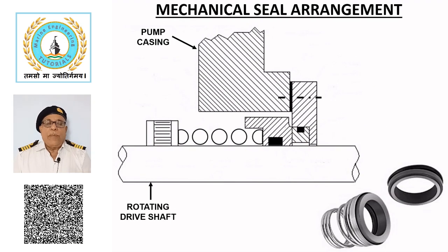Mechanical seal arrangement. This sketch shows the mechanical seal arrangement which is used when leakage is undesirable or gland packing is unsuitable due to high pressure.